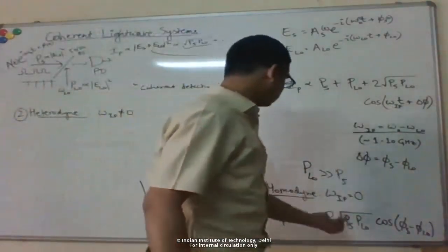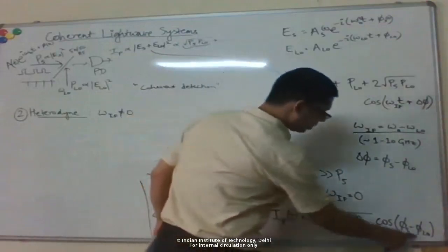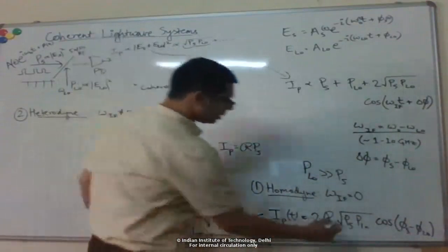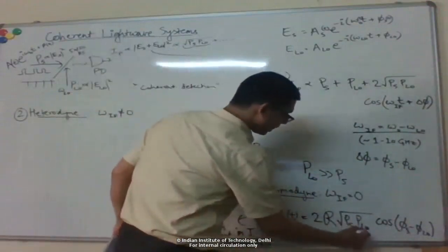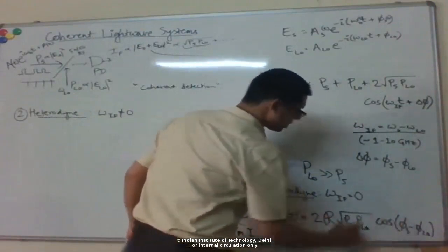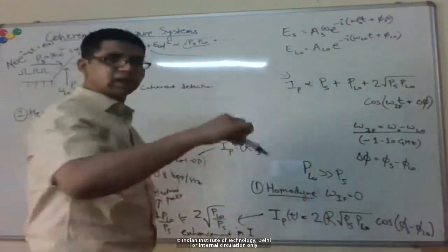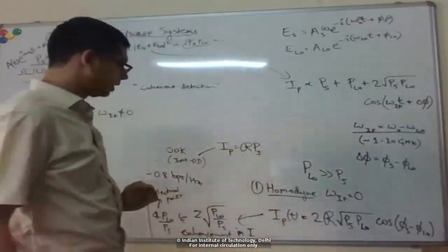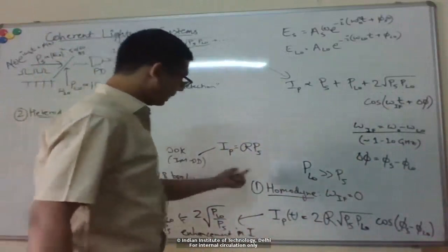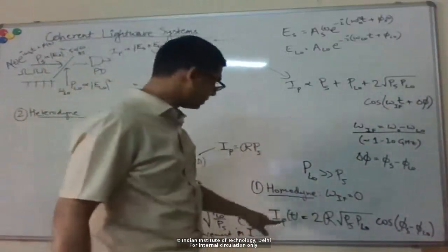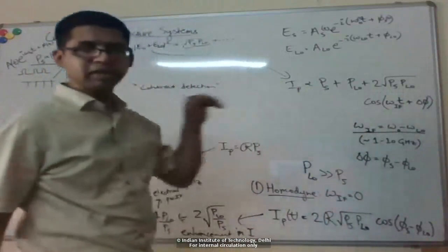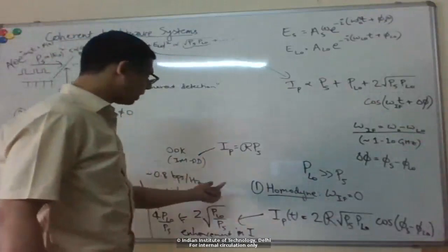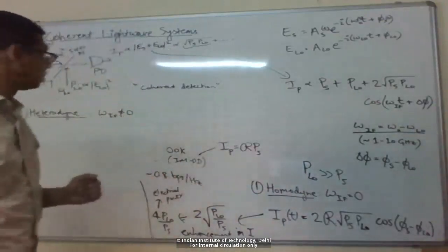you can see that actually even here, the sinusoidal time dependence goes away, right? So now, depending on how you encode data, the time dependence will be here in the power or in the phase here. But this sinusoidal time dependence is not present in homodyne detection, right? So in some sense, for every bit, this is like a DC photocurrent, right? Within a bit, it's not changing. So for DC photocurrent, we know that the electrical power is I square R.